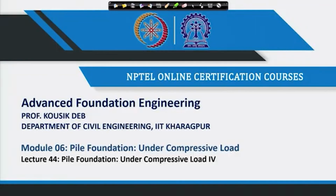So, last class I discussed how theoretically we can generate a load settlement curve for a pile. In that approach we divided the pile into a number of segments, and for each segment we calculated the settlement at the center by assuming a tip deformation. Then we get the ultimate load carrying capacity Pu of the pile and the settlement of the pile at the top, based on one particular assumed tip deformation.